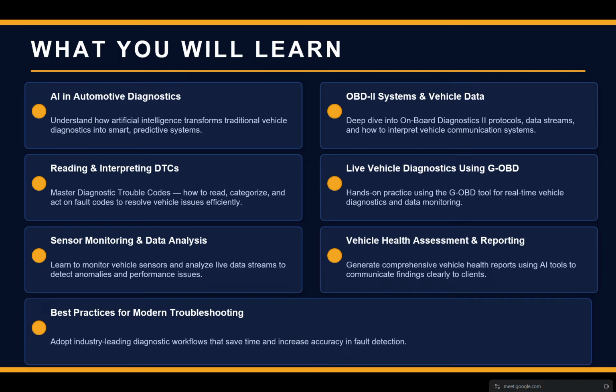So how to interpret fault codes and read them, that's one of the things we'll be looking at. Then sensor monitoring and analyzing them, talking about how we are going to look at the data coming from sensors, knowing what the normal range of values is at different conditions, so that when you have a fault coming from somewhere, you know where that fault is coming from.